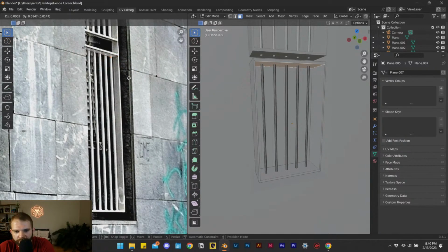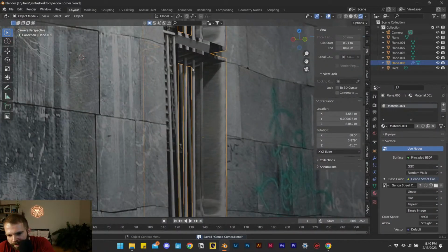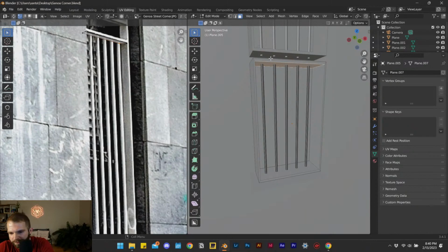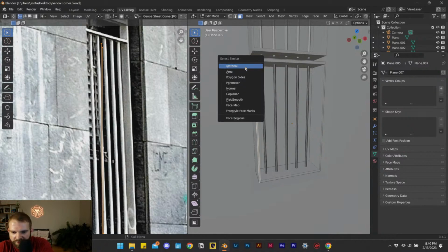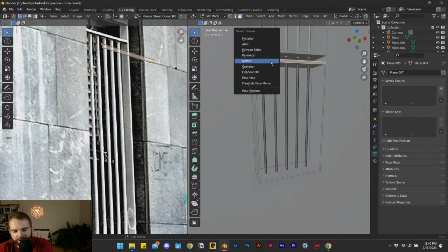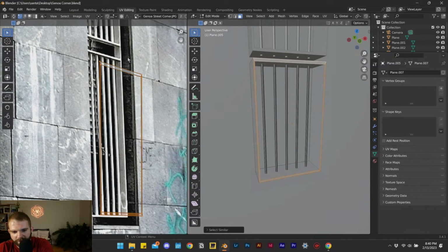And again, there's a little bit of wonkiness to deal with. Ooh, I've got a few more surfaces I have to fix, which would be everything front facing just needs to be white because it's catching a lot of photo and that's adding a lot of detail to the edge that isn't looking great. So we'll hit normal. What I did there is I selected one surface, hit Shift G to select other ones that have those same qualities, and I can hit normal and it selects all the other faces that are looking that way. So now I can move this here and just have these corners fit into the edges of the frame.